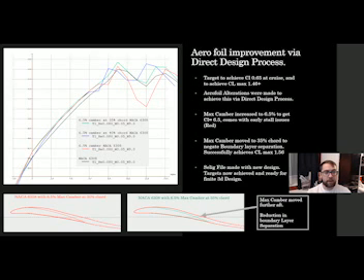Adaptations to further the aerofoil's performance. Increasing max camber to 6.5% chord length provided ideal CL at 0 alpha, but max CL is now 1.35 with an early stall behaviour. Observing the on-point view in direct design, boundary layer separation was taking place towards the leading edge of the chord, causing an early stall condition.